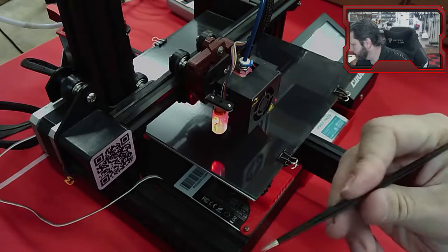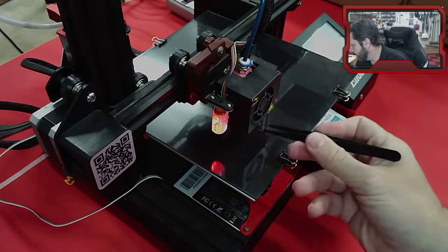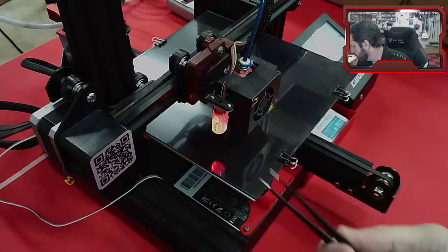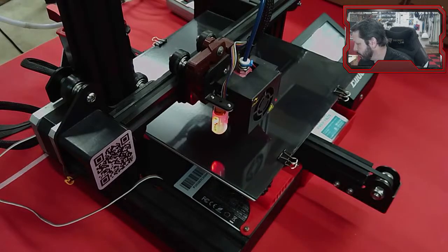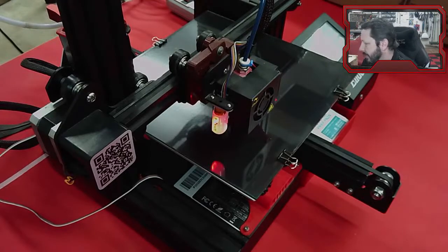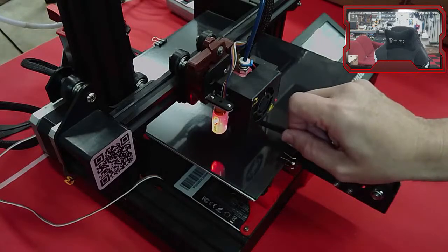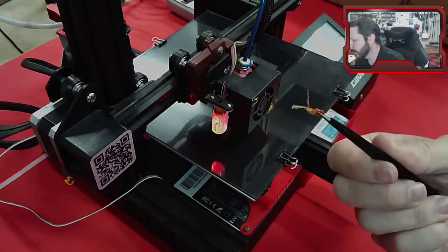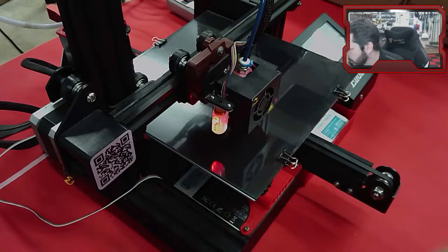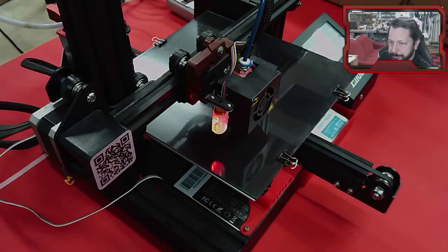But if they don't, then that is pretty handy to get in there and clean junk off the nozzle before it's starting to print, because it does get really hot. And it cleans off a lot easier when it is hot, because that's when the plastic can actually be melted and pulled off of there. So see, all of that junk was on the nozzle, and I don't want that in my print.